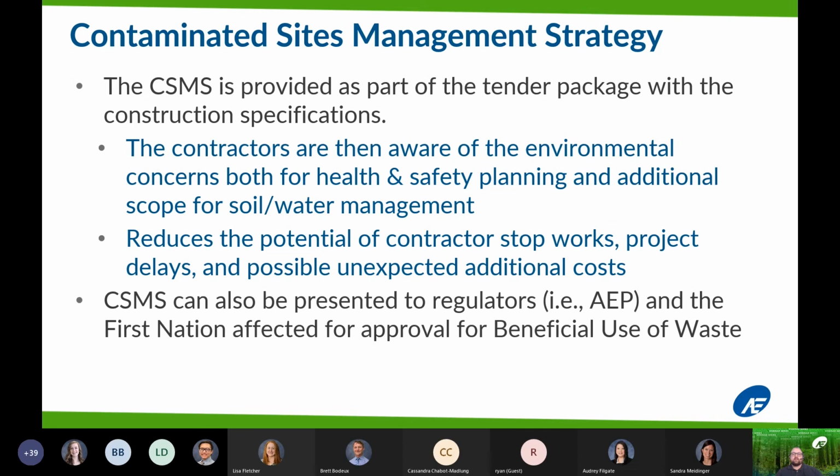So the contaminated sites management strategy is provided as part of the tender package with the construction specifications. The contractors are then aware of the environmental concerns, both for health and safety planning and for determining the costs of their bid. The contaminated sites management strategy can also be presented to Alberta Environment and Parks for approval for beneficial use of waste, which is a policy to use soils for other purposes, such as for commercial roadway construction, as long as it doesn't cause additional impacts to environmental receptors.